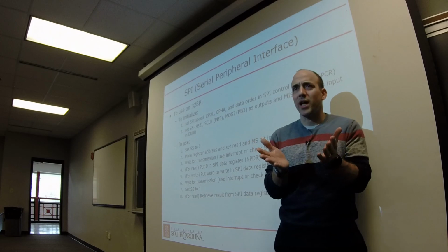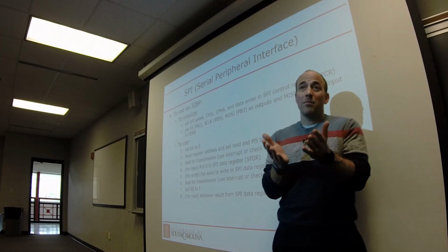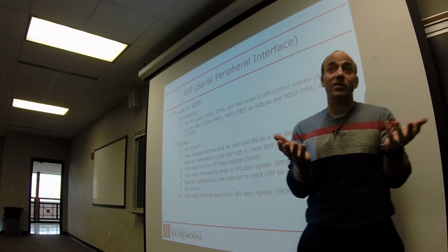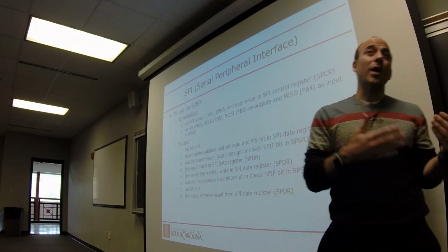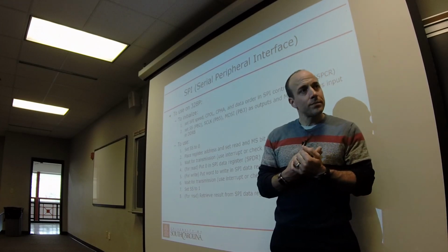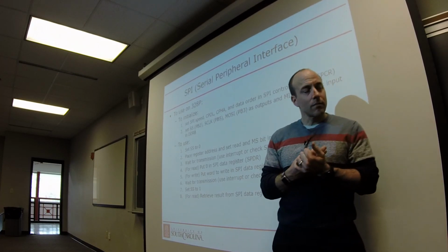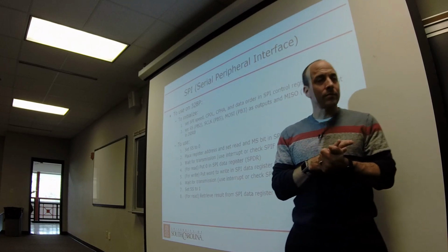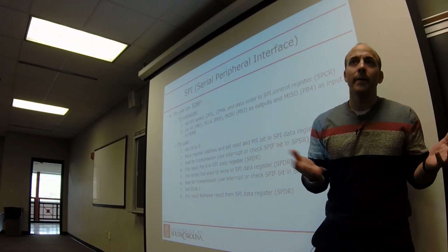The SPI bus is running at 4 megahertz. So the amount of time it takes is basically, well, it's 4 clock cycles per bit, and there's 8 bits. So it's basically 32 clock cycles, right? So there's no point in using an interrupt to have it wake you up after 32 cycles. I would also point out that the overhead for even using an ISR at all is something like 15 to 20 clock cycles just to handle stack stuff. Yeah, putting everything on the stack and then restoring it afterwards. So it's hardly worth it, right? You might have 15 cycles to do something, right?